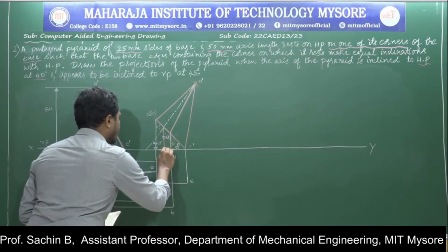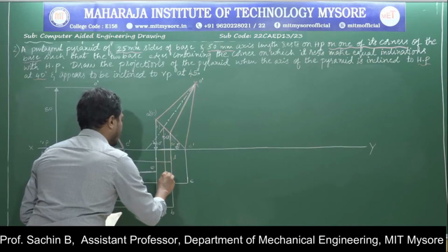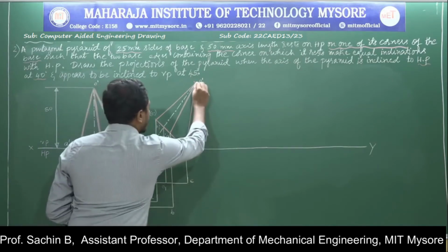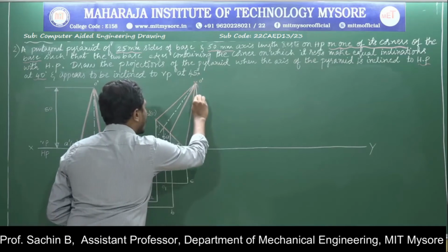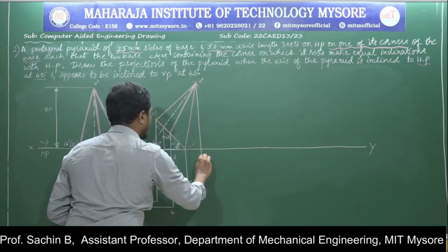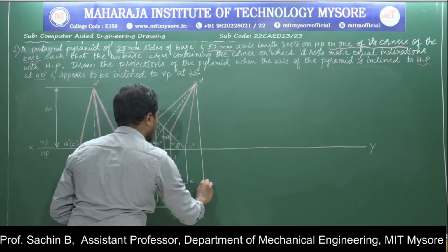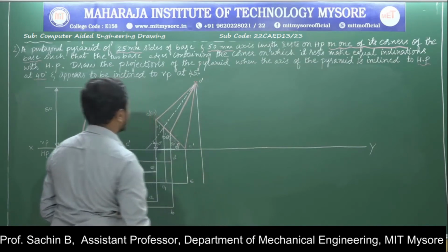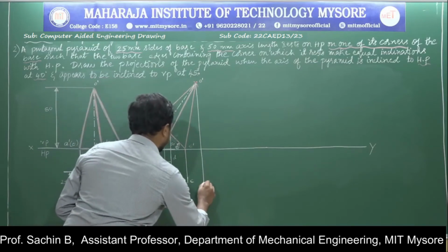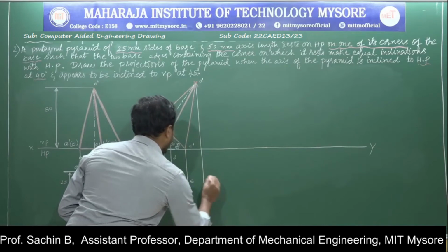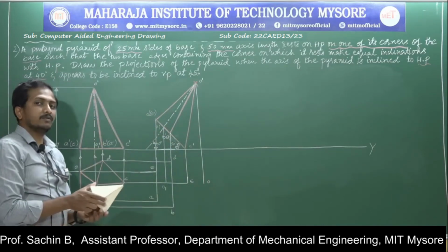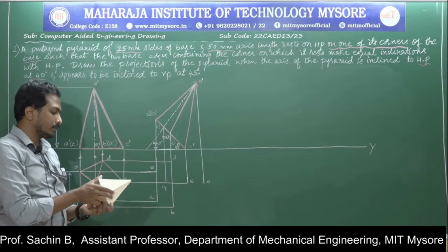If I draw the axis, it will lie exactly here. This is O1 point. Next one more thing is left, that is from O I am drawing the projection line from the top. This is O. Now I will go for applying the visible and invisible concepts.